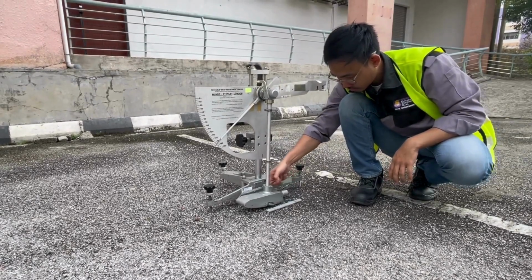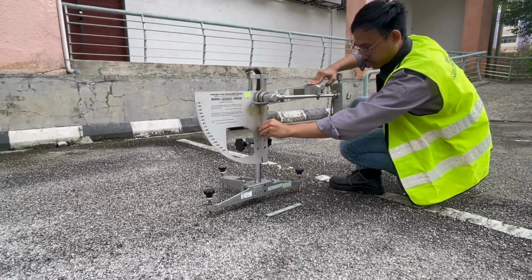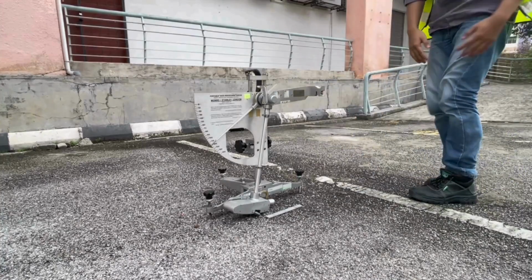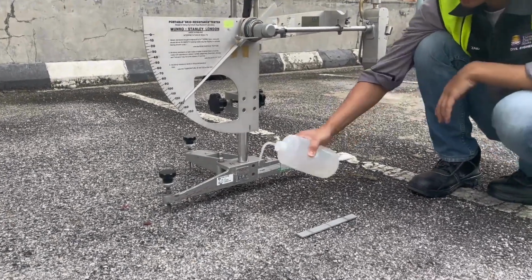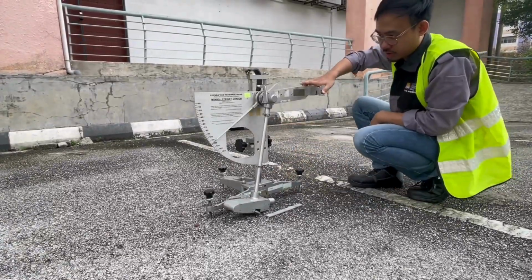Adjust the height of the pendulum by lowering the arm until the slider just touches the surface over the precise distance on the scale rule which is placed alongside. Release the pendulum arm and record the reading. Make 3 swings and record the mean of the successive readings. Repeat step 4 by wetting the surface, and record the data for 3 swings.